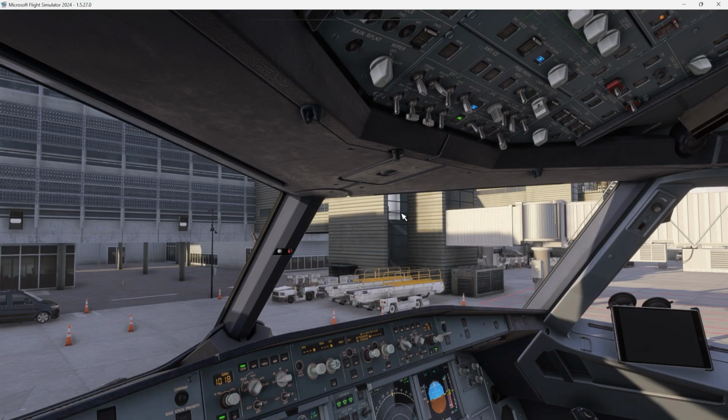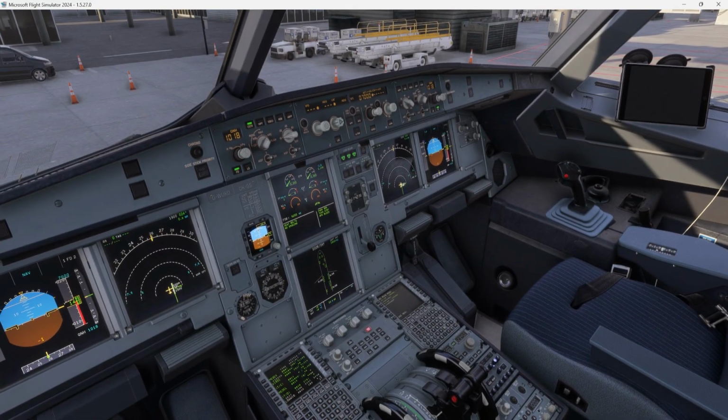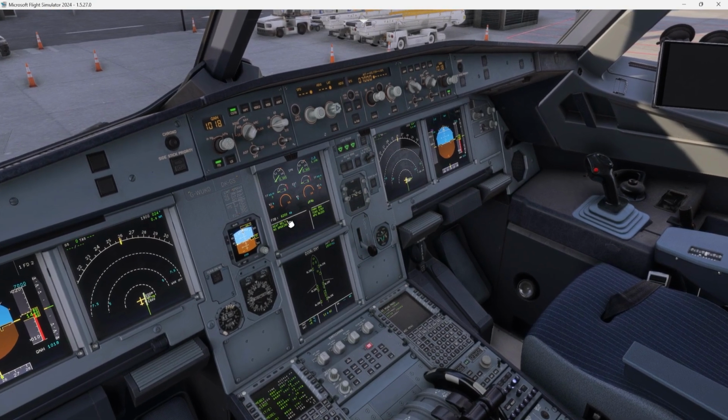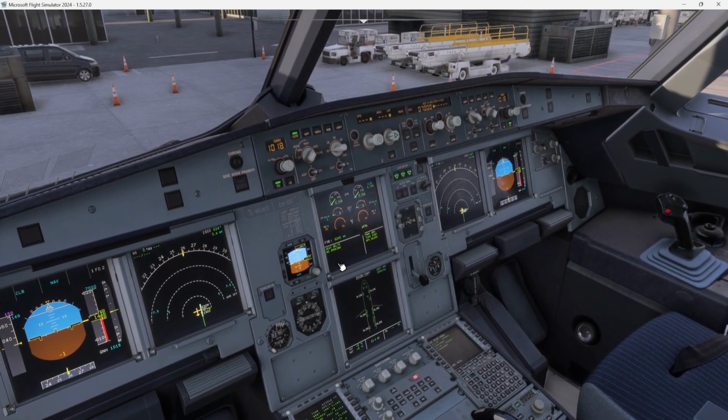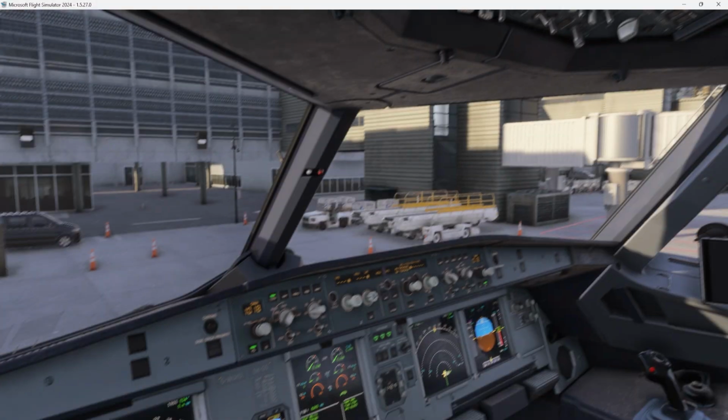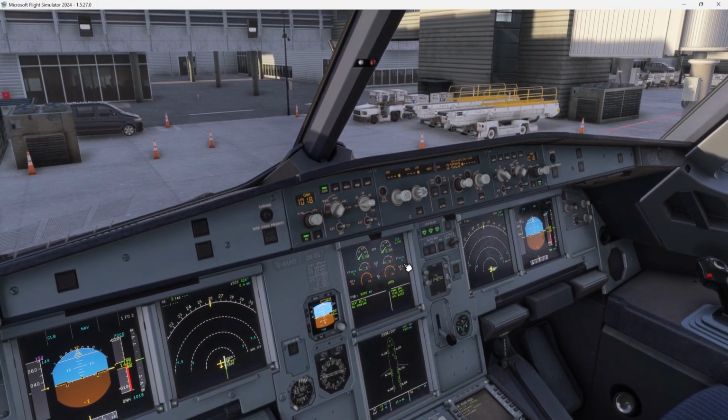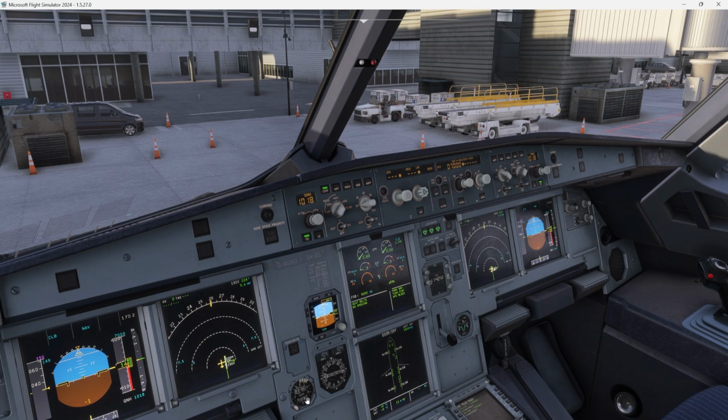Let's go with the cockpit preparation checklist very quick. Gear pins and covers are removed. Fuel quantity 6.2, we have it here, 6.2. Then seat belts on, we have it in the ICAM also. ADIRS nav position checked. Baro reference 1018. Okay, thanks. And cockpit preparation checklist completed.